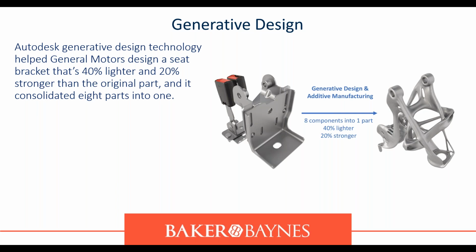Imagine what's possible when this kind of technology is applied to the whole vehicle and whole supply chain. The very first image that you see there is the seatbelt bracket. With generative design, they created the image on the right-hand side, including all of those parts on the left, which is 8 different parts, into 1 part. And it's 20% stronger and 40% lighter.